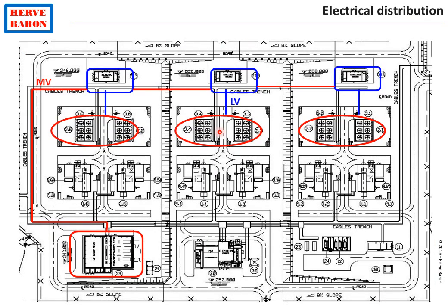Large power consumers are identified on the plot plan. For instance, here, the large power consumers are the air-cooled heat exchangers. Electrical substations are located next to these high power consumers, so that the length of the low voltage cables is minimized.